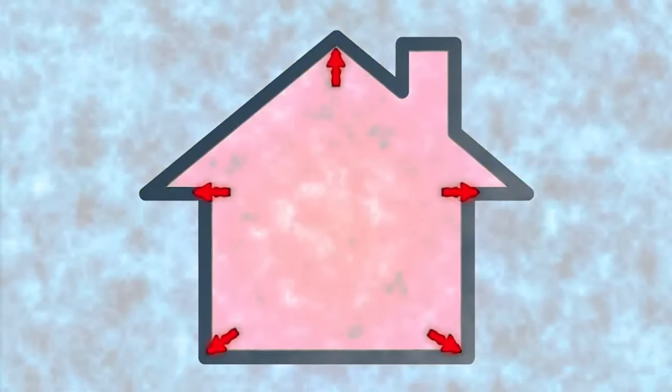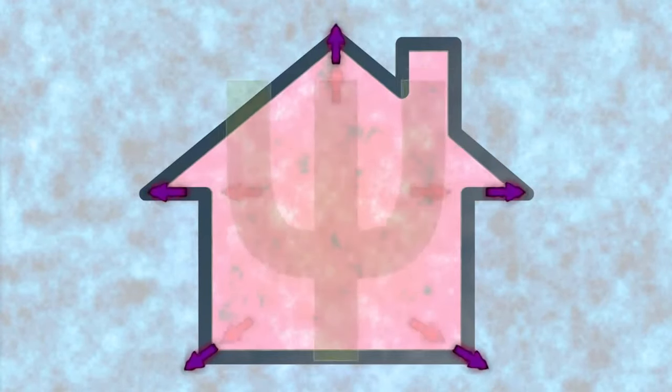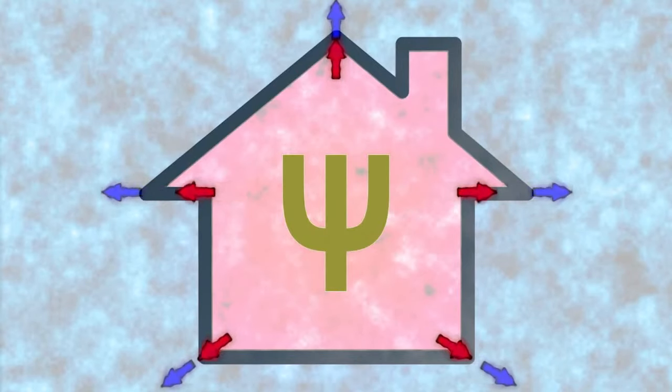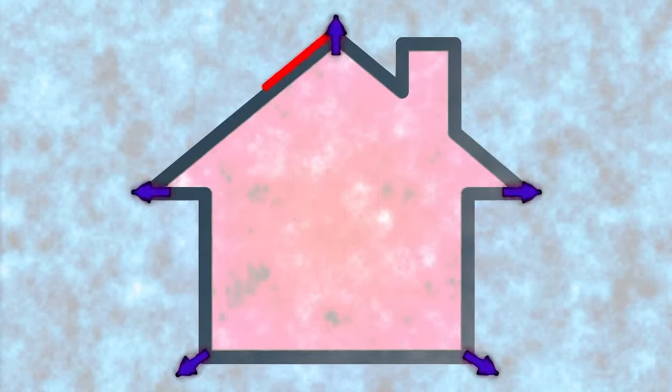Thermal bridging at corners and junctions is accounted for using an additional value for linear thermal bridging, known as a psi value. But in most cases, these are addressed using standardised pre-assessed details to limit heat loss. The easiest way to visualise the way thermal bridge-free design works in practice is to simply imagine drawing a pencil line around a cross-section of the entire heated envelope of the building. If that can be done without touching anything other than insulation, the design is free from thermal bridges.